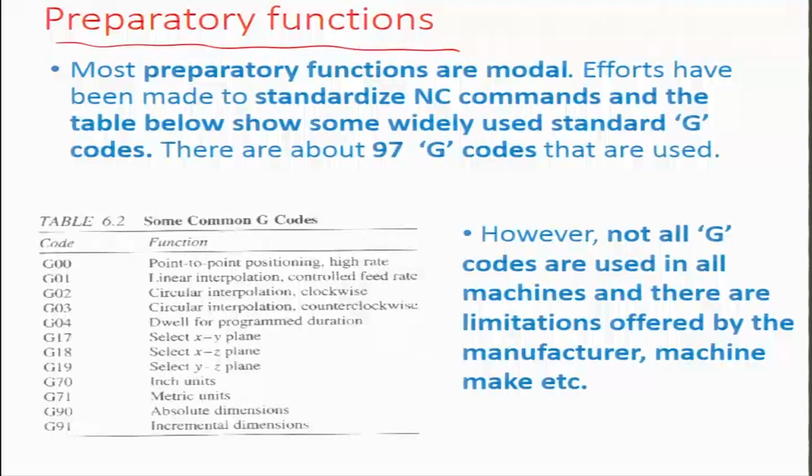So what I didn't explain earlier, and I can probably take it up now, is that there are 2 different classes of commands, one called the modal command, another called the non-modal command, depending on whether the commands keep existing if not entered again, or if not changed. So there is a counter, you have fixed some numbers and the number keeps on being taken by the code every time, up to an extent you don't change it. So these are modal, so in time they are progressing. There are of course non-modal, where once it has been executed, the command would stop and the next step would typically have to be entered back.